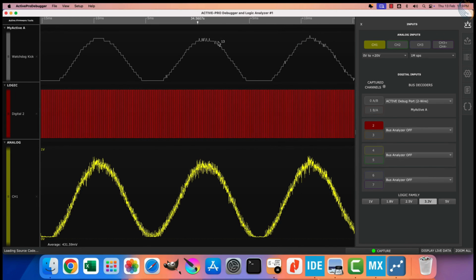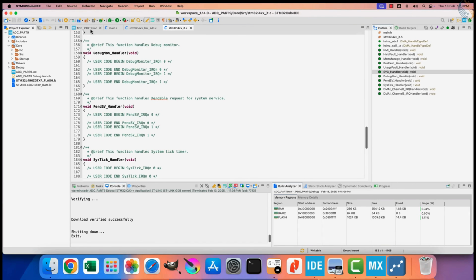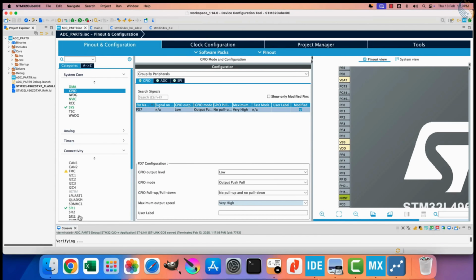The STM32 reference voltage is set to 3.3 volts by default, therefore for the 1.1 volts the maximum value we can get is 1/3 of the maximum value. So we have seen how in the low resolution, the ADC is not able to differentiate between small voltage variation.